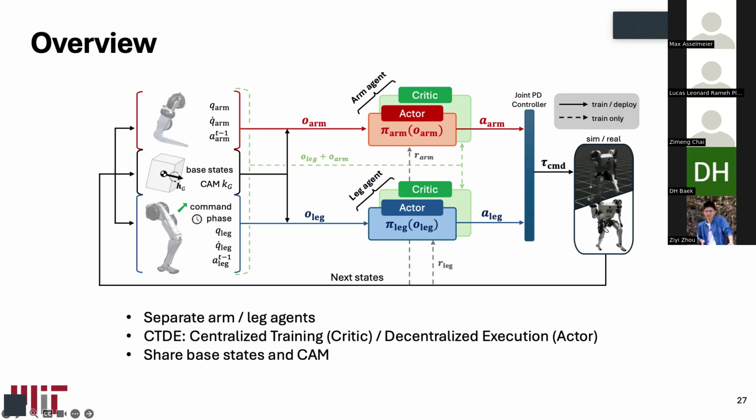For instance, the arm doesn't see the leg-specific information, but you only give the centroidal angular momentum information, so that we can interpret centroidal angular momentum as a kind of latent information about your counterpart. Say if you are pulling a rod with each other, you don't really need to know how your counterpart is moving their arms and legs, but you just need to understand the tension in the rod. So that kind of intermediate, low-dimensional information is shared through this centroidal angular momentum part.